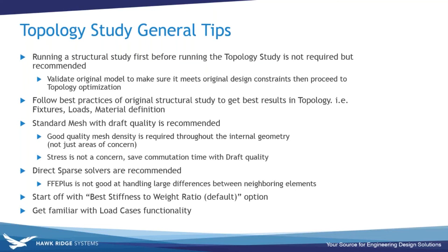The other thing is follow the best practices of the original structural study. So if you've taken our classes or you already have a good feel of running just a normal stress test, follow that same best practice because it's going to be needed in the topology study. We still need to define fixtures. We still need to define the loads and the material definitions. So making sure that your materials are okay or in the right units, things like that, right? So still follow that best practice in terms of how is my model going to be constrained? How is my model going to be loaded to best replicate what's happening in real life, right?